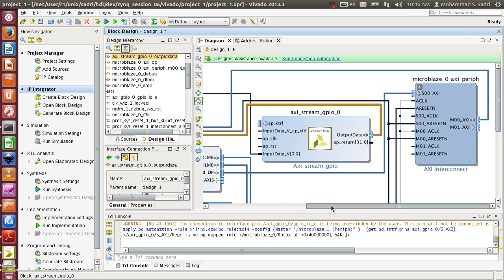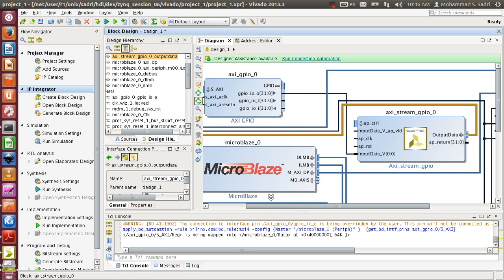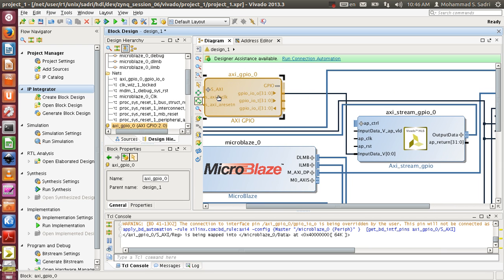So practically what we are creating right now is a simple method to convert the AXI memory mapped interface to an AXI stream interface. Of course, there are much better, much more efficient methods, but inside the HLS you can increase the width of this to whatever value you want, and also you can drive this port with maybe another GPIO module if you want, or you can tie it to one, and then you have the conversion from AXI memory map to AXI stream directly.